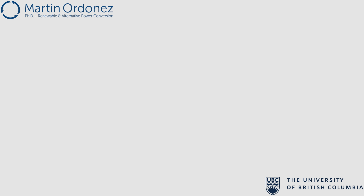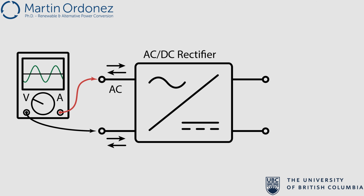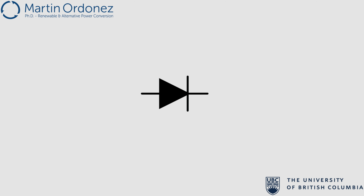Hi everyone, this is Sayed Abbas Arshadi, and today I'm going to talk about diode rectification circuits and their performance. A rectifier is an electric circuit which converts an alternating current or AC voltage at the input into a DC current or DC voltage at the output. This rectifier circuit typically utilizes an electrical component called a diode in order to convert the AC input into a DC output. A diode, which is usually indicated using the symbol seen here, is a passive semiconductor device.